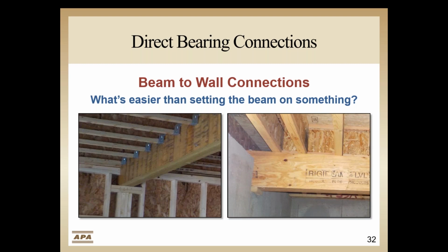Consider the allowable crushing for an LVL is generally about 750 psi loaded in the tangential direction versus 425 psi for, say, an SPF wood plate being loaded in the radial direction. As opposed to bearing directly on the studs loaded in the longitudinal direction, which would be the strongest strength of the wood, we have loaded the detail in the weakest direction.